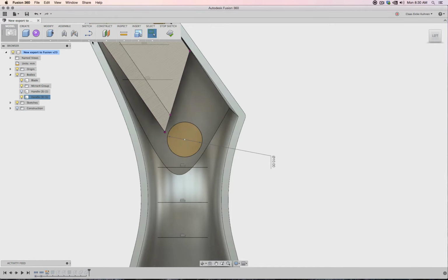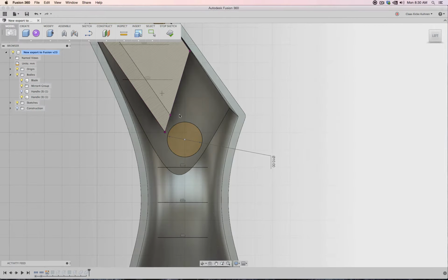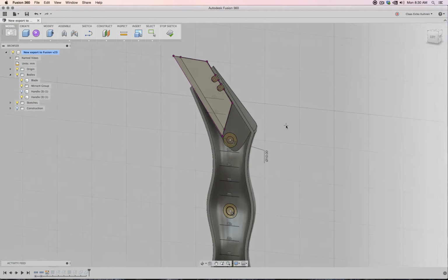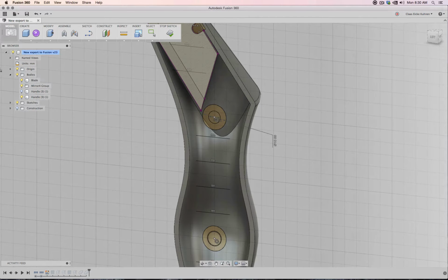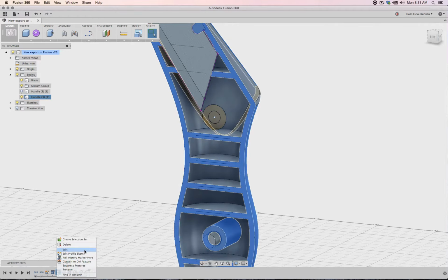So it's a centimeter. Of course, now you need to know what type of ring you would like to have a screw. So I'm going to create another in here, let's say 5 millimeters, enter. Okay, perfect. Good. So I'm going to click Stop Sketch. Everything is being updated, and then I can actually go to here and say Edit.